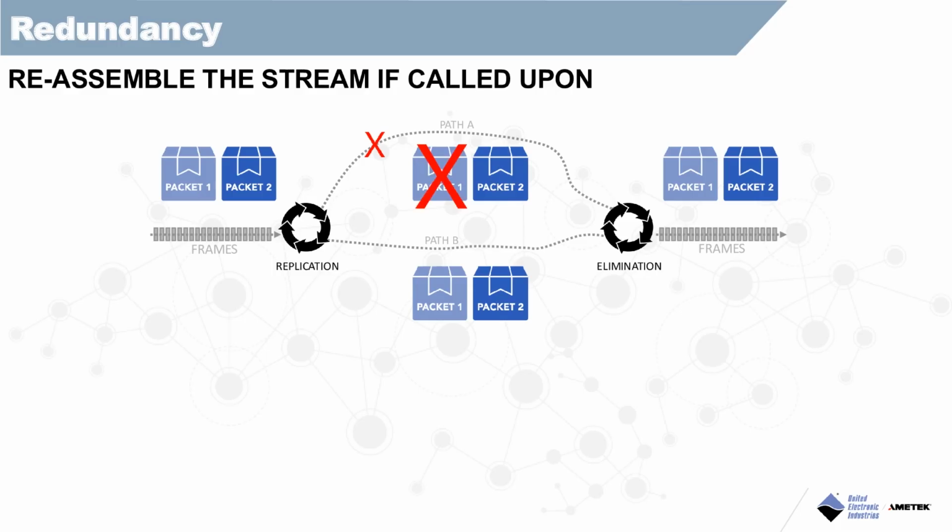Another test would be dropping a packet or a frame, or maybe the same one on both paths. Another good test is to act as an end node without a BR profile. Well, what will your device do? If you recall, this profile adds sequence numbers onto time-critical packets. Good tests include sending the wrong sequence number on a packet or even on one of the replicated packets.